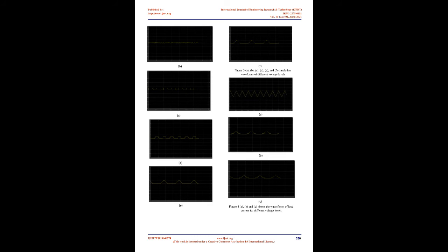Y. Lei et al. [16] have designed a 2 kW, 60 Hz, 450 VDC to 240 VAC power inverter, and tested it subject to the specifications of the Google/IEEE Little Box Challenge. The inverter features a 7-level flying-capacitor multilevel converter, with low-voltage GaN switches operating at 120 kHz. The inverter also includes an active buffer for twice-line frequency power pulsation decoupling, which reduces the required capacitance by a factor of 8 compared to conventional passive decoupling capacitors, while maintaining an efficiency above 99%.